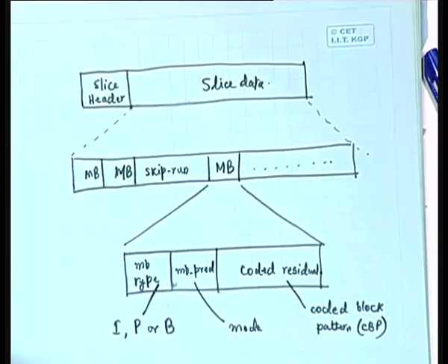How many blocks is also flexible, because a macro block is 16 by 16 luminance and 8 by 8 chrominance from the 2 chrominance channels, whereas the 16 by 16 itself may contain up to 16 luminance blocks, or fewer depending upon how we partition the macro block: a single 16 by 16, or 2 16 by 8, or 2 8 by 16, or 4 8 by 8, and every 8 by 8 can again be partitioned, as I already mentioned.